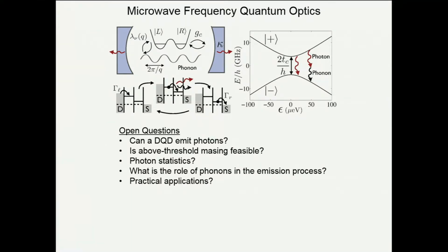So what we're going to do is take our quantum dot device, in this case a semiconductor double quantum dot, trap a single electron in it, and couple it to a cavity mode, a high quality factor cavity that we can trap light in. The energy of the photons in this cavity is closely matched to transition energies associated with the charge states in our double quantum dot.